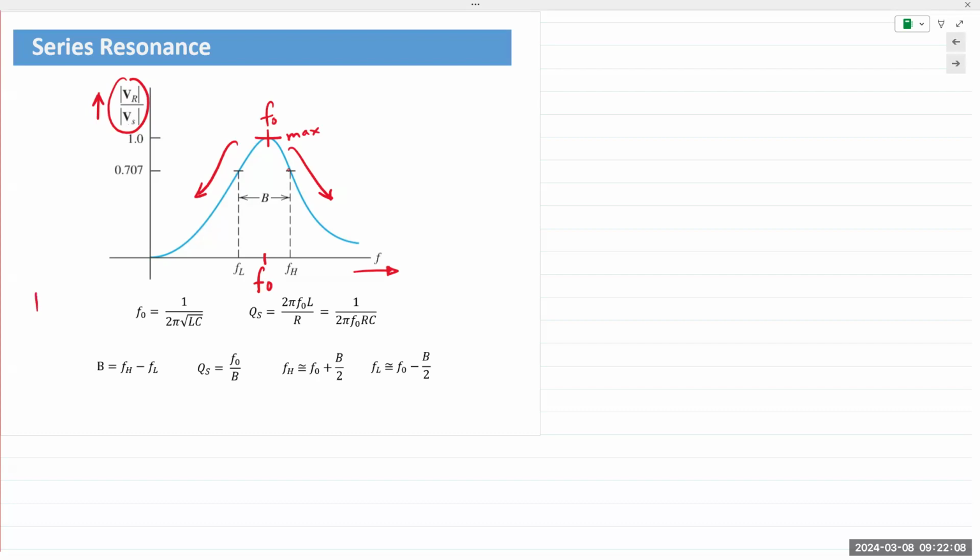That resonant frequency, f0, is a constant, as in fixed for a particular circuit. So it depends on the value of the capacitor and the inductor. So f0 is 1 over 2π root of LC. In the same terms, I can describe omega 0 as 1 over root of LC.